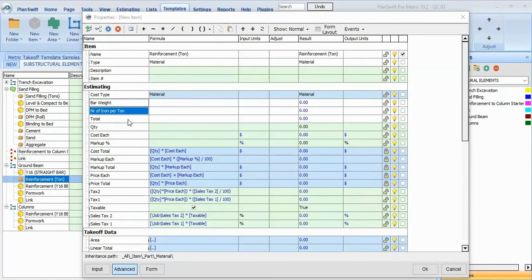So for the reinforcement, we created all we need. To get our total, it's going to be number per ton, multiplied by weight per weight, and multiplied by the length. You know that one length of reinforcement is 12 meters, but these days they are not 12 meters again, they are around 11 to 11.5 meters. So I multiply by 11.5 meters.